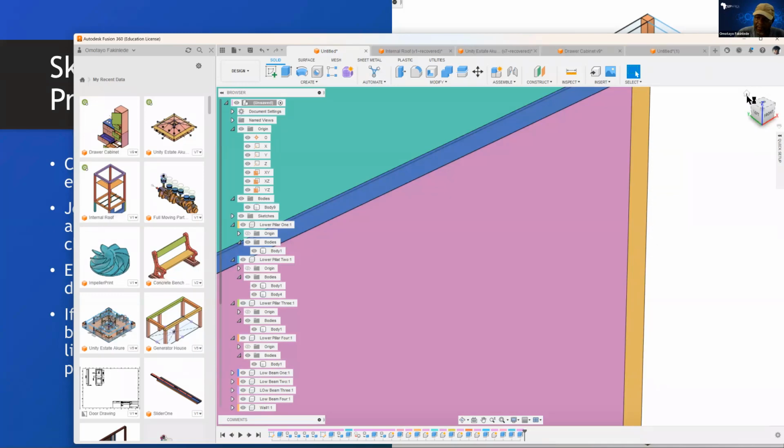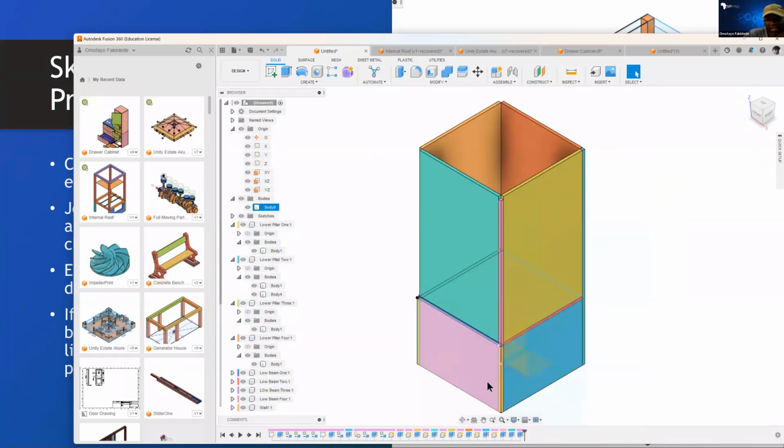let's see. So you can see, we created this wall by beginning from the surface of the pillar here, but instead of specifying the distance between the two pillars, we say start from this face here and end at the face facing it on this other pillar. So in that case, you use the object as the delimiter of how far your extrusion will go, rather than a distance. That is something I just created to explain to you how this was created. So let me remove that, because that's not part of the drawing. Control Z. So I've removed that.